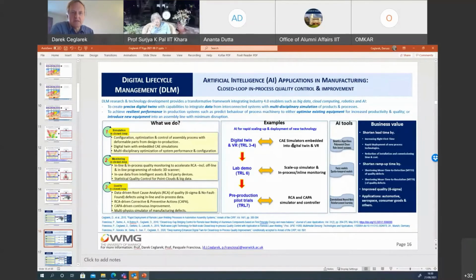So let me give you one example, which will be easier to follow, of what I mean by the scaling up here in this vertical direction. If I do coupon checking or testing, nobody is producing coupons later on; people are producing whole sub-assemblies. So if I use a coupon at this level, the errors between the coupon and the real sub-assembly can be 15%, 20% or more in many cases. Why? Because you have a different geometry, a different heat distribution, and a number of different things which cannot be replicated one-to-one. So what industry is doing is coupons, and they have challenges to fix it.